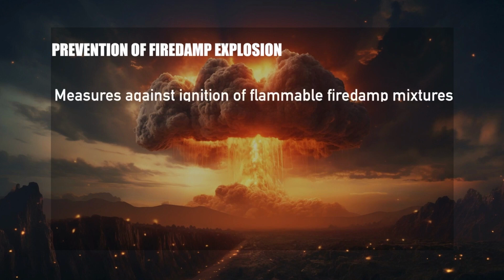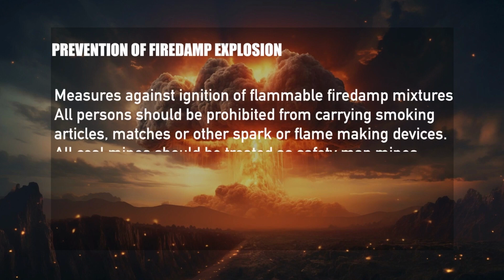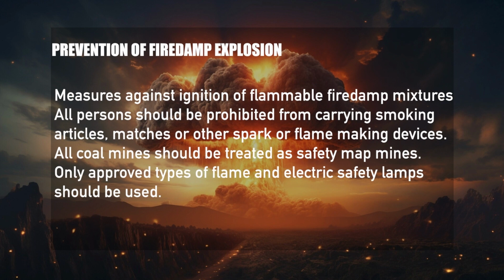Measures against ignition of flammable fire damp mixture. If a sufficient amount of fire damp has accumulated, then we should take such action that ignition of fire damp cannot take place. All persons should be prohibited from carrying smoking articles, matches or other spark or flame making devices.